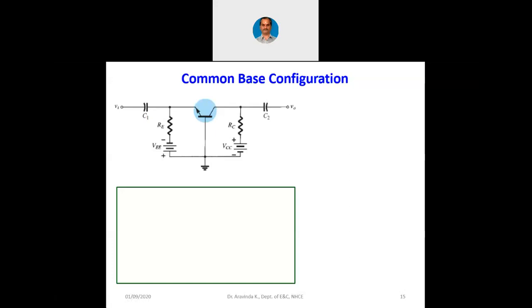It is our reference. Now when we take it as a reference, you may think, sir, the base is connected to ground, will the transistor switch on? You may think that way. The answer is, the transistor will switch on because ground is not 0 volts. That is why I have been telling you again and again, don't think that ground is 0 volts. If ground is 0 volts, the transistor will not turn on at all. We simply put a symbol here just to indicate that it is the reference point for our measurement. I keep repeating this so that you will remember it.